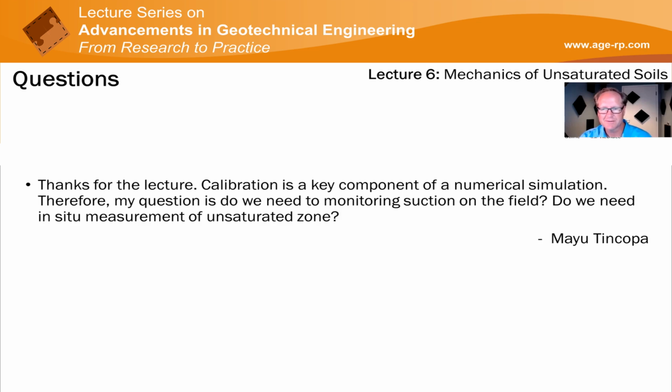Another question. Calibration is a key component of numerical simulation. I would agree. Do we need to monitor suction in the field? Do we need in situ measurement of the unsaturated zone? Yes, this is a common question. The answer is yes, but it's difficult. It's a little more difficult to measure the changes in soil suction above the water table. And this is often forgotten.